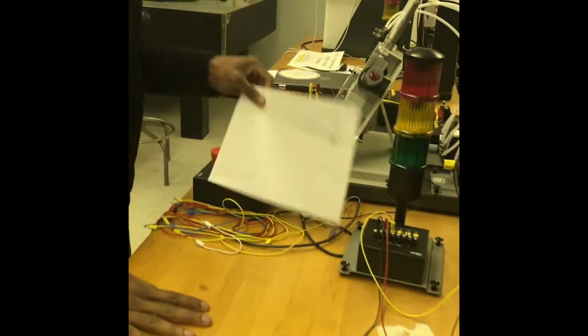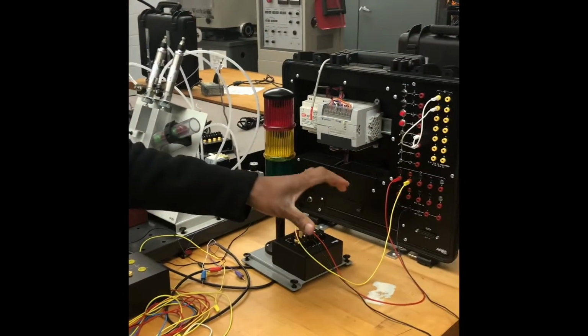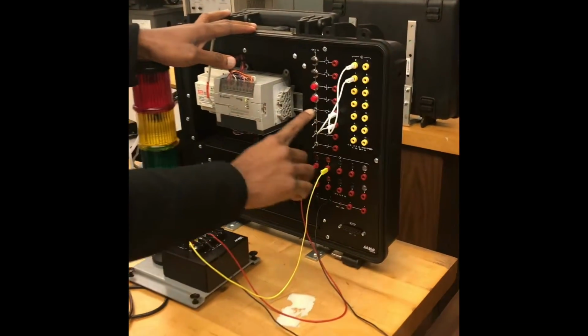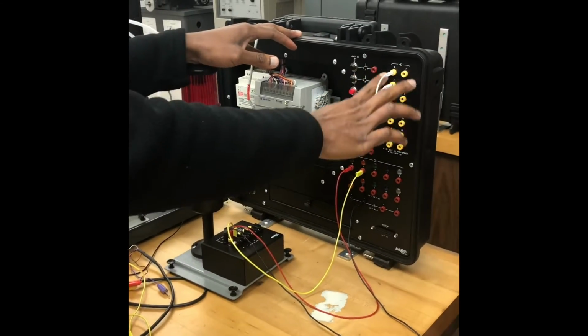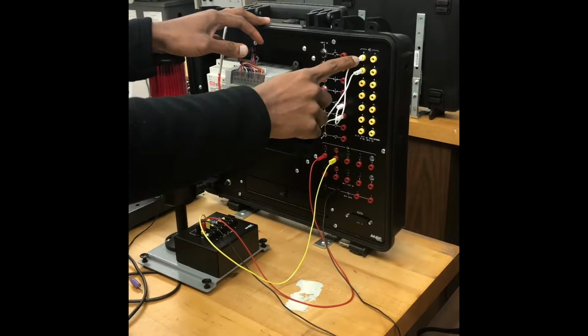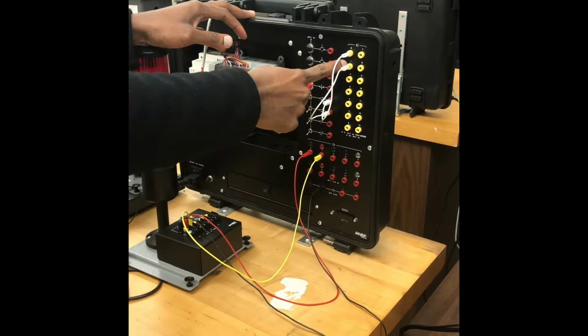Just like in the first instance on the Automation Studio, where you can connect your circuit using the symbols, here is where we actually have to connect our circuit. If you notice here, these are some switches that are provided on our PLC kit, and we have some of the input ports for our PLC. I0/0 is actually this input right here. 0/1 is this input.